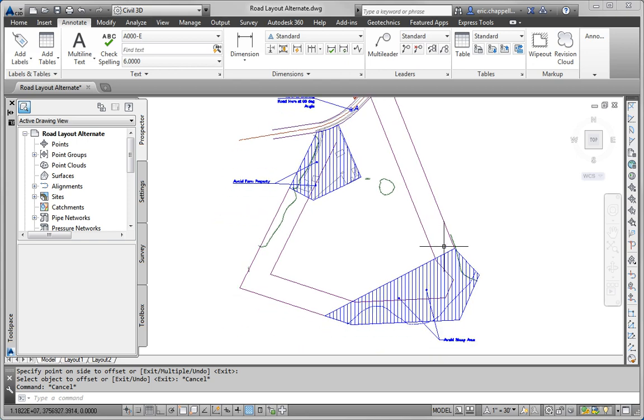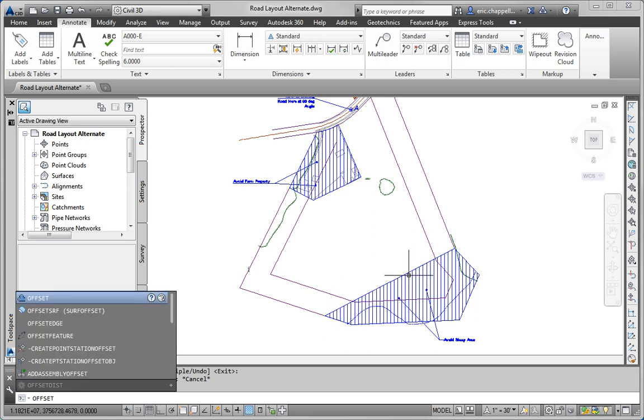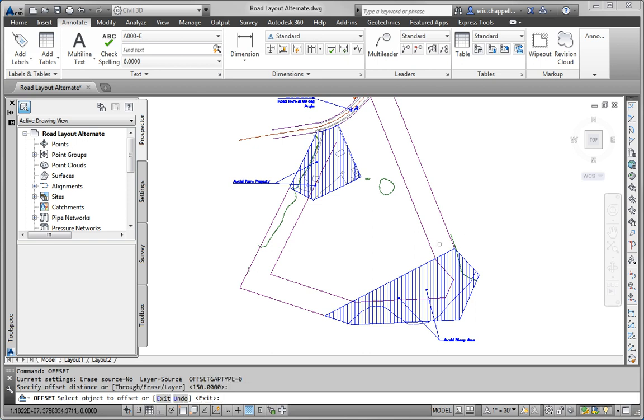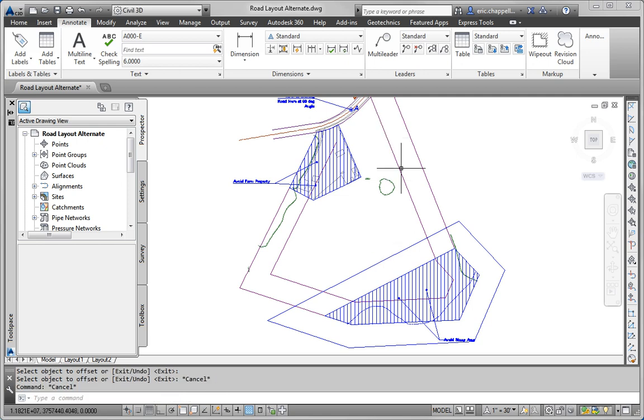Here we've got the steep area, and I'm imagining the road center line coming around here and this being the backs of the lots here. So I'm going to do the same thing, offset 150 feet from the edge of our steep slope area. Okay, so now I'm picturing the alignment coming around here to this location. So I've got a fair amount of open space here that isn't developed. So what can we do with that?